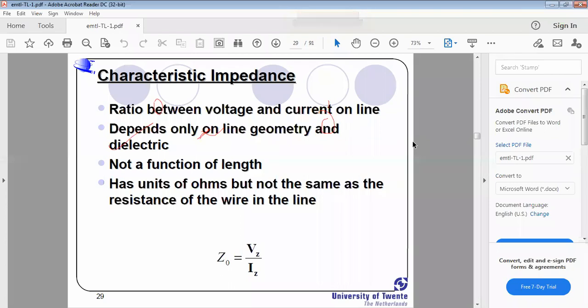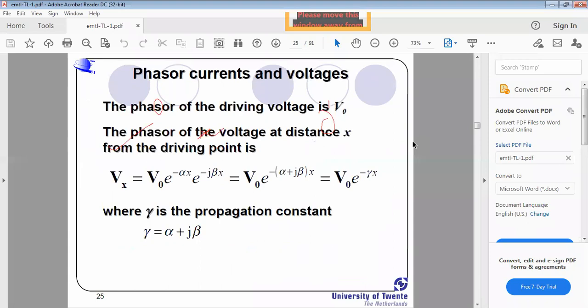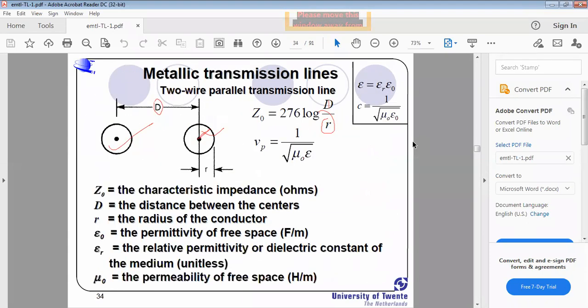What we learned in today's class: characteristic impedance, velocity factor, and propagation constant, including the derivation of parameters for both lossy and lossless lines. The basic form of the expression is the same for lossless or lossy, but when we apply the condition R equals 0, G equals 0, that is called the lossless condition. That's all about today's class. I will continue in the next class, where we will discuss the reflection coefficient and VSWR terms. Thank you.